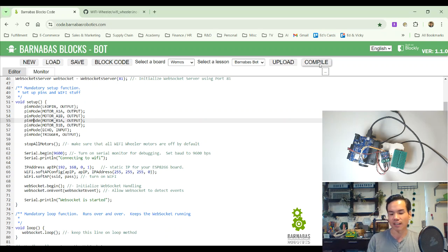Now here's the thing. USB cords come in two main forms. One is a full working USB cord that has power and also has communication. That's like the one I gave you in the kit. I know the ones I gave you in the kit work correctly, so you're good there. But if you use another USB cord, it might not work, because some USB cords are only meant for charging devices and not for talking to them, like if you just want to plug into the wall with a wall charger and charge a micro USB device.